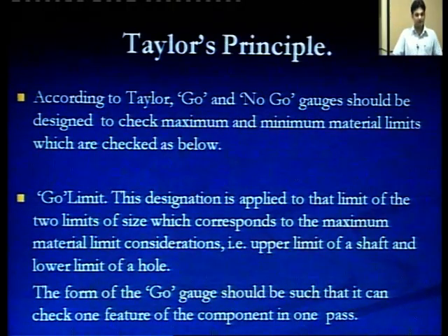Now, what is the go limit? This designation is applied to that limit of the two limits of size which corresponds to the maximum material limit consideration, that is, the upper limit of the shaft in case of a ring gauge and the lower limit of the hole in case of a plug gauge.